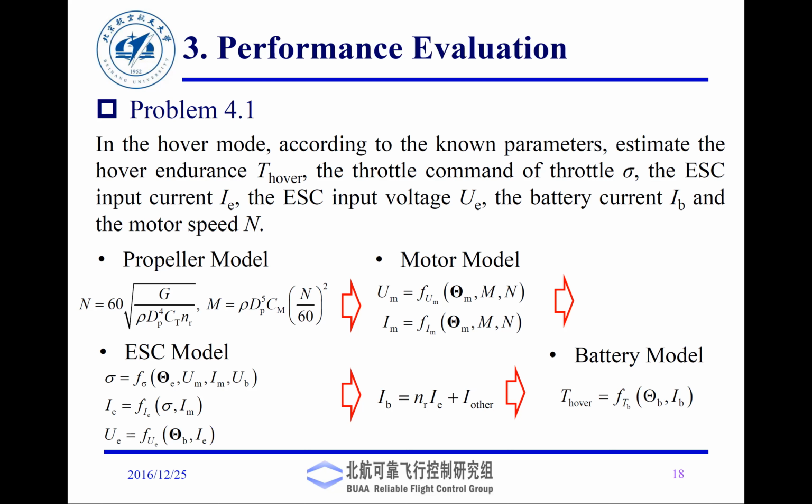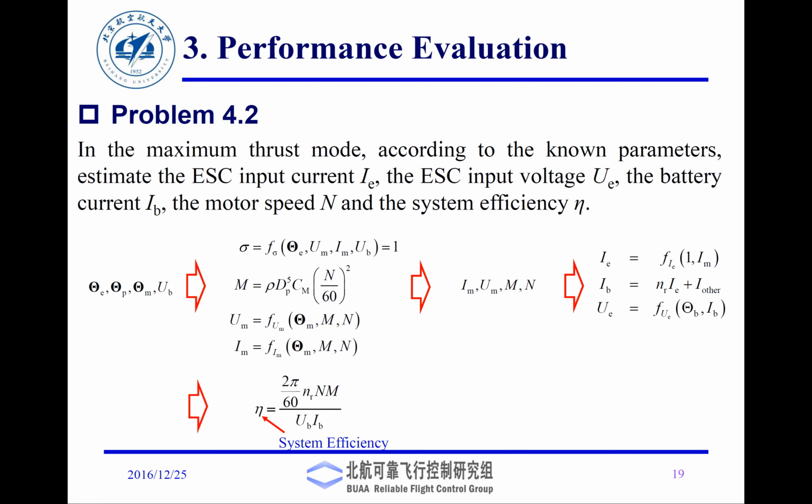The next part that you look at is the maximum thrust that the UAV, or that system, is capable of giving out. Once you have your basic parameters decided, you want to find out what is the maximum thrust that can be generated. So what you do is you change the throttle value from 50% to 100% and then find out what is the thrust that is generated.